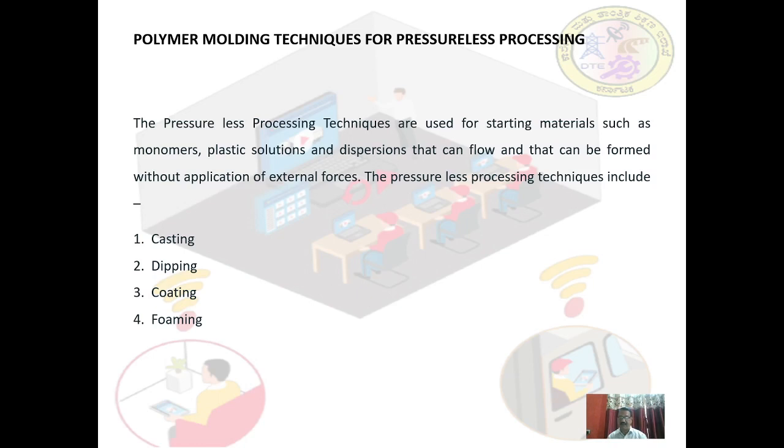These are made using two-part metal molds which are heated and filled with the paste. The paste gels on the outermost edge, forming a skin, and subsequently the excess paste is poured off.